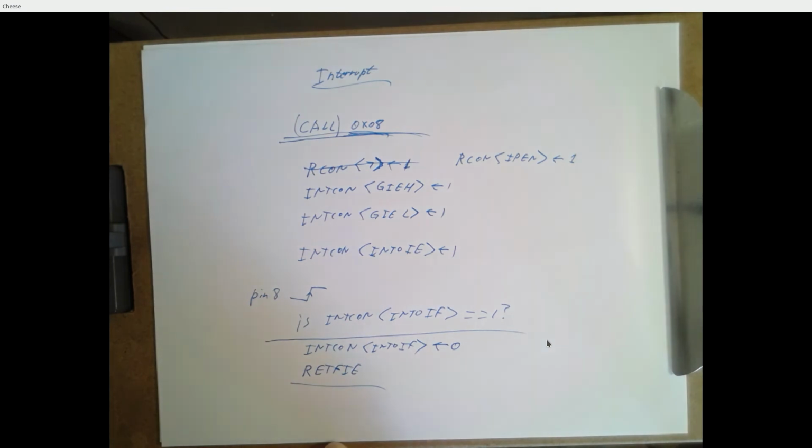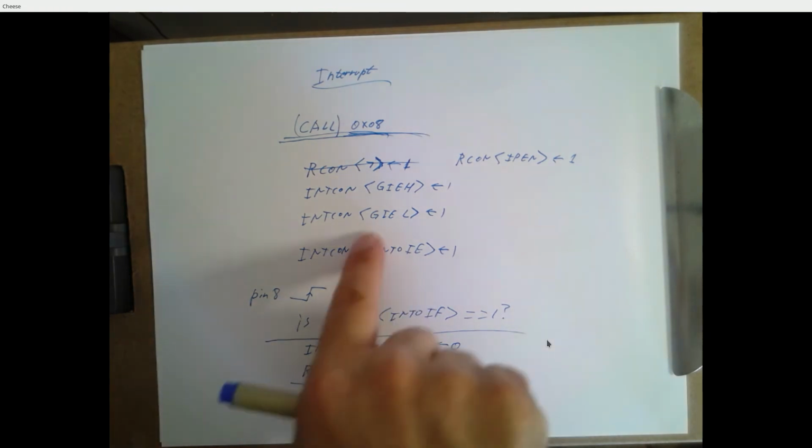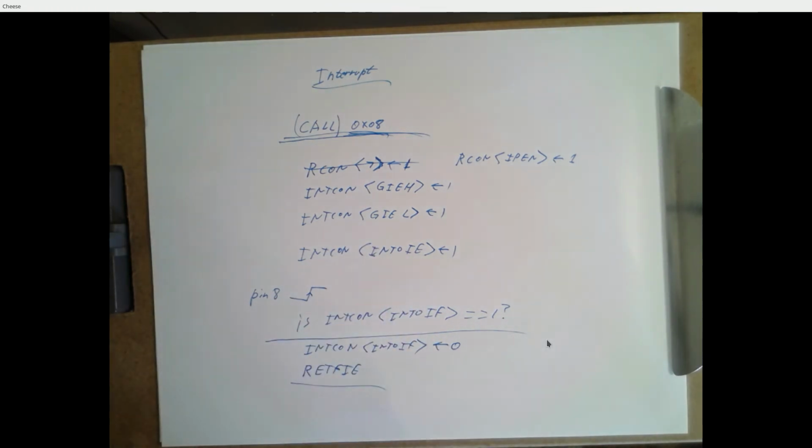If another interrupt occurs, you won't get interrupted until you finish what you're doing right now. So basically, interrupts are disabled while you're inside an interrupt routine. RETFIE re-enables interrupts and then does a return, but it does it as a single instruction. If you try to do it manually, it's possible you can get interrupted before you execute the return, and then you've got a problem.